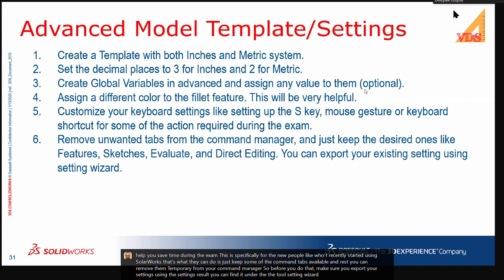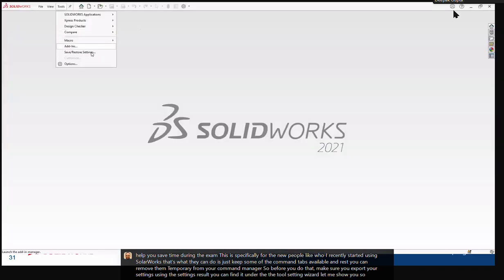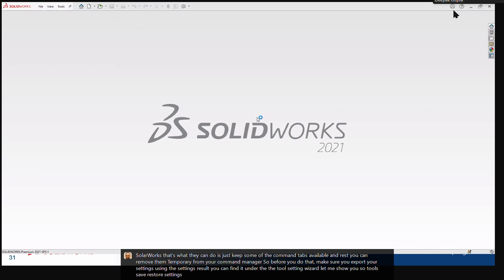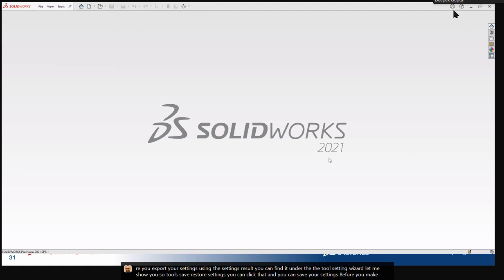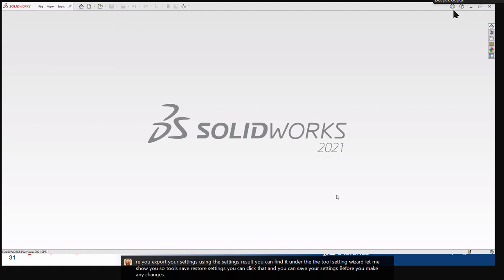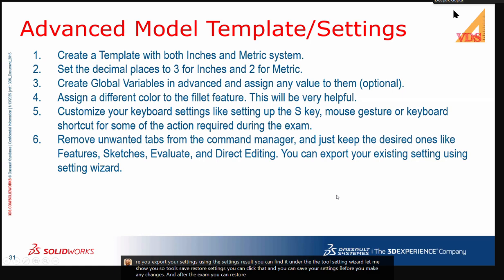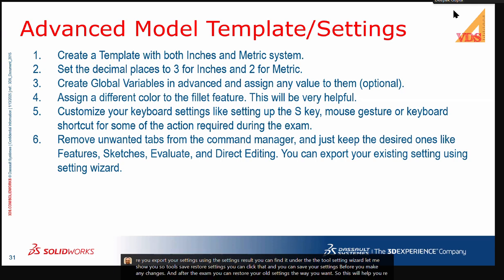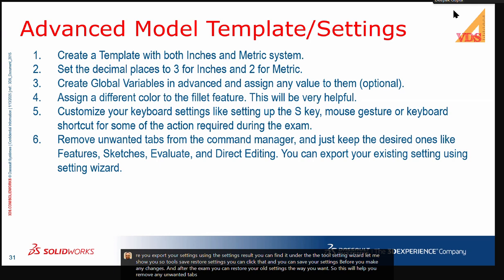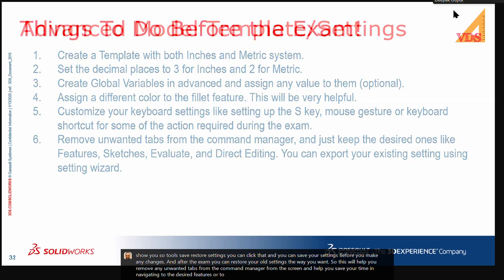Let me show you. So tools, save, restore settings. Here you can click that and you can save your settings before you make any changes. And after the exam, you can restore your old settings the way you want. So this will help you remove any unwanted tabs from the command manager from the screen and help you save your time in navigating to the desired features or commands.